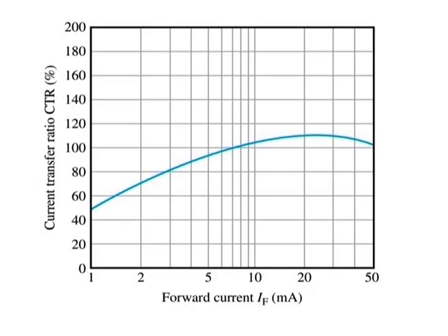Optocouplers are used to isolate sections of a circuit that are incompatible in terms of the voltage levels or currents required. For example, they are used to protect hospital patients from shock when they are connected to monitoring instruments or other devices. They are also used to isolate low current control or signal circuits from noisy power supply circuits or higher current motor and machine circuits.